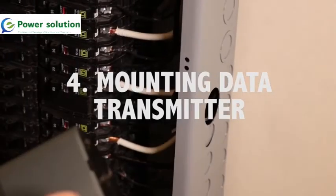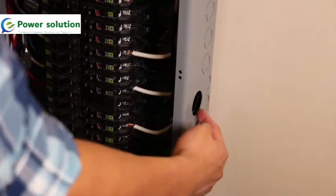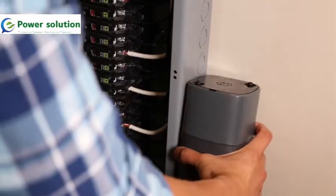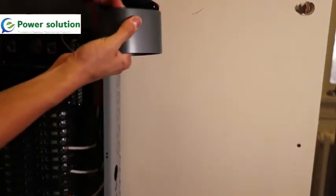For this installation, we've identified our optimal location for our transmitter, and we've created a 1-inch knockout in the panel to establish a connection through which we will have our transmitter get sensor data. Take the field wiring compartment off of the top of it, and we can go ahead and pop off this top too, so we can work within our base transmitter.